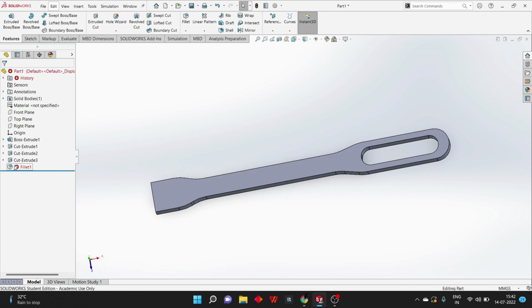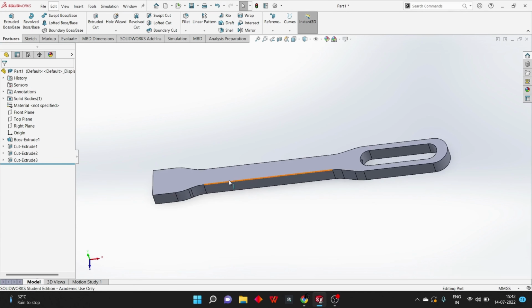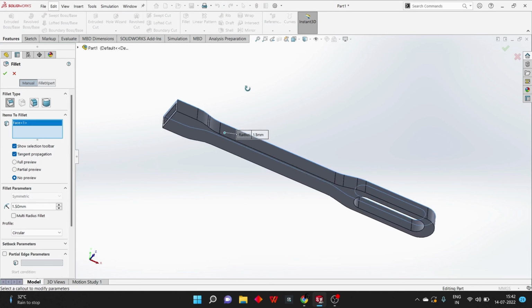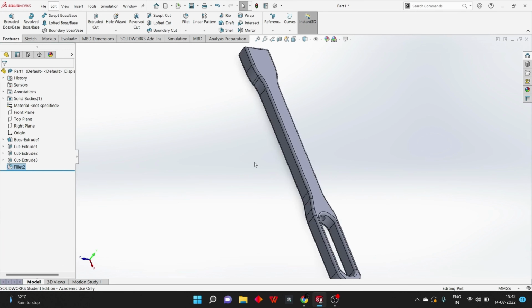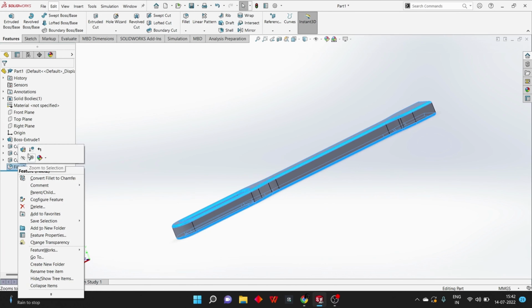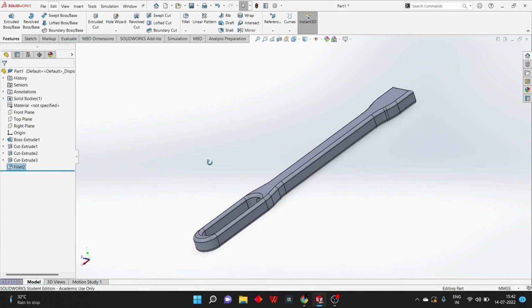alright, so the fillet which we made prior was not able to compile the edit which we did afterwards. So we'll just delete this feature and add the fillet again. We'll just go to fillet, select the faces and give it a fillet, and we have it. So we have a fillet. You can increase or change the fillet here, and you're good to go.